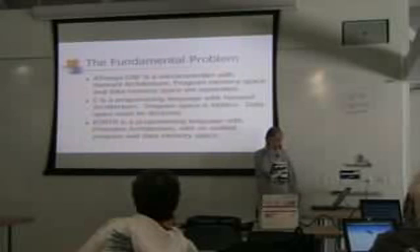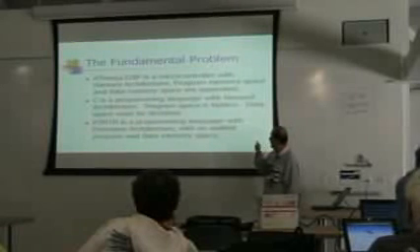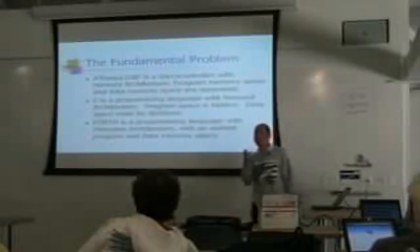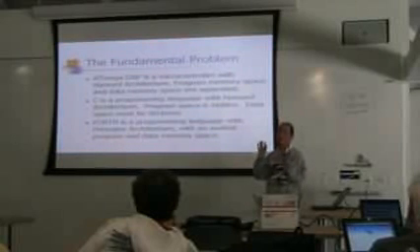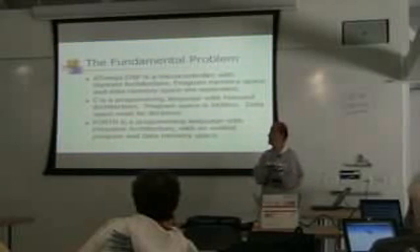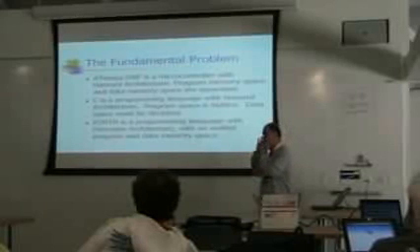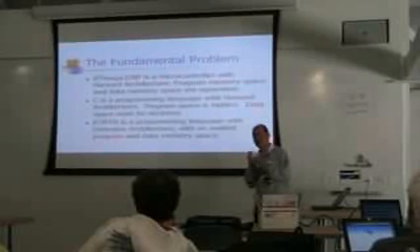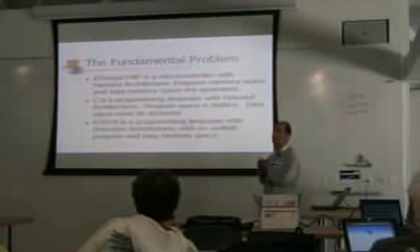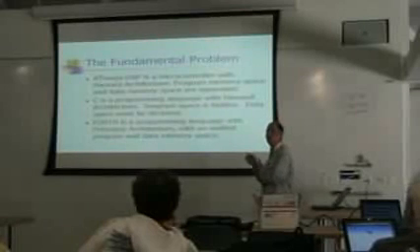So the problem is that the ATmega328 is a microprocessor of Harvard architecture. So it has a separate program memory and data memory. You can read and write only into the data memory, and you can execute only from flash memory.